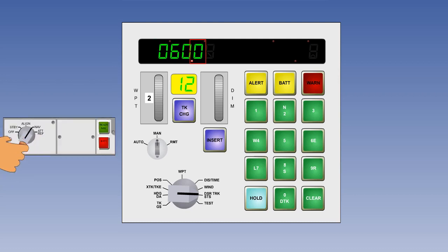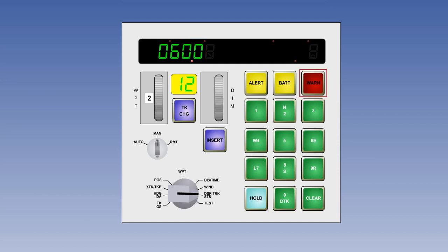We mentioned earlier that system status can give an indication of time remaining to align. However, once NAV has been selected on the MSU rotary switch, STS is used to indicate serviceability and for fault diagnosis. If the INS is serviceable, the code, usually 0000, appears in the right-hand LED. Its main use, however, is for fault diagnosis in conjunction with the red WARN light.